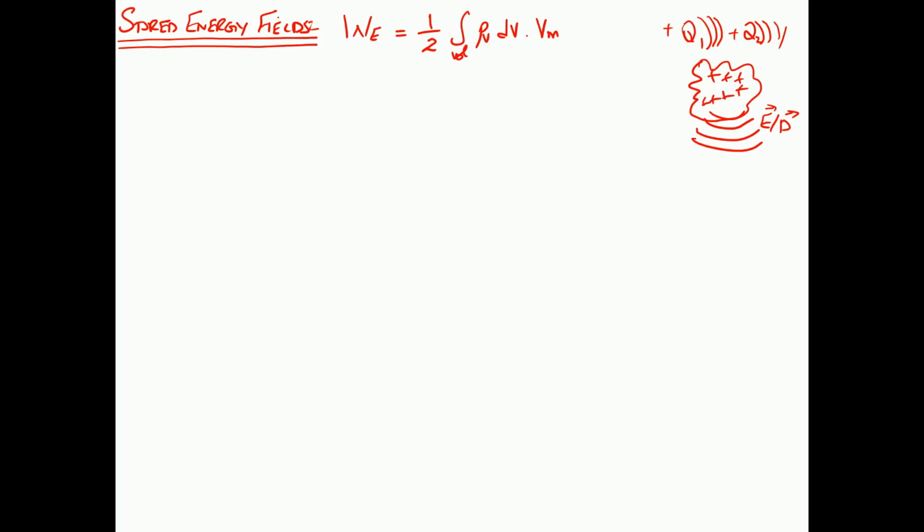Yes, we can. From our base equation which we saw previously, which defines the continuous energy stored, I can rewrite it as the stored energy represented as 1 by 2. Since this is a volume charge distribution, I can represent rho v in terms of Maxwell's first equation, which means I can write rho v as divergence of D, then you have the potential V, and then dv.